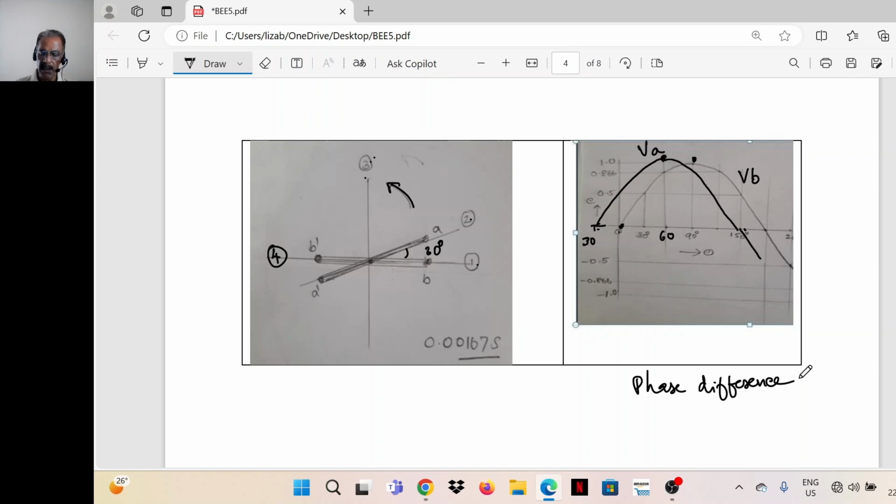If we represent the voltage as RMS phasors, then if I take VB in the reference position, the voltage induced in coil A is leading the voltage induced in coil B by an angle of 30 degrees, because VA comes to any position first, then only VB. Let's take a third coil, an identical coil, C dash.